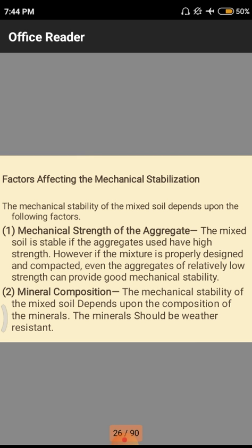Likewise here also we have to go for different design parameters. According to those design parameters, we need to design layer by layer in proper mixes, so we replace only 10% of soil and keep 90% normal soil. Then we see what kind of strength we are getting. After that, if the strength is not sufficient, we have to improve it, with 15% of another soil and the remaining 85% normal soil. Likewise we have to go for different variations. In which condition we are getting maximum strength, we have to observe, and implement that in the site.